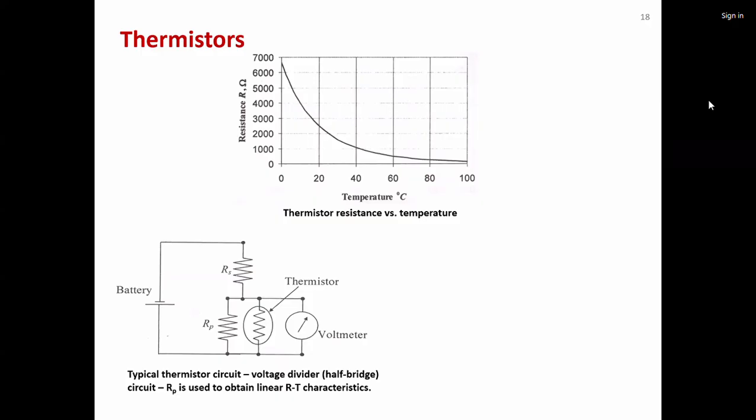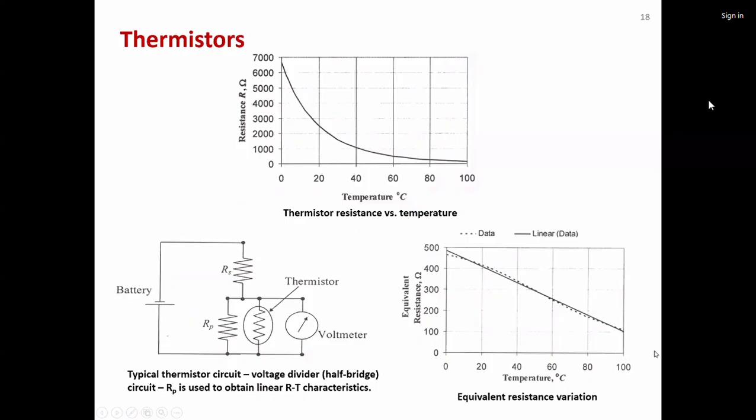So if you have bought a thermistor, you can actually build a circuit to make the net response of the circuit linear, something like this. So this is the thermistor, and you can have a shunt resistor here, basically to limit the amount of current. In parallel to the thermistor, you can have this RP, a resistor, and resistors are basically made out of metals, and their resistance would increase with increase in temperature. So that is contradictory to the thermistor.